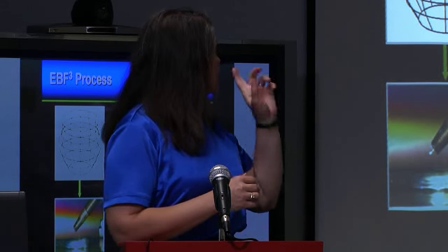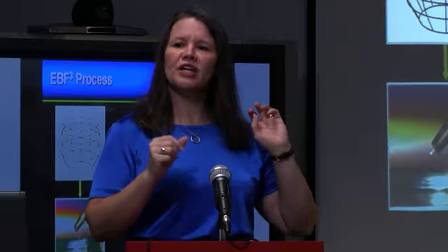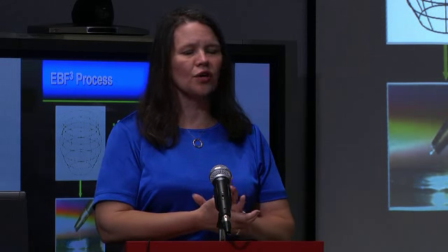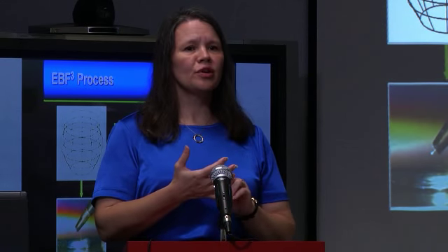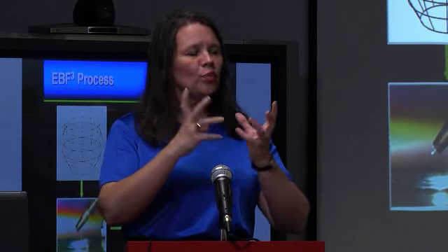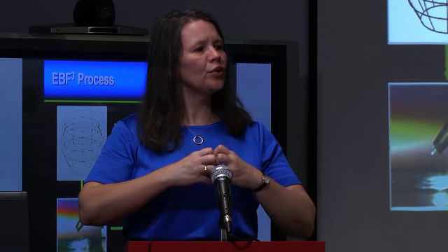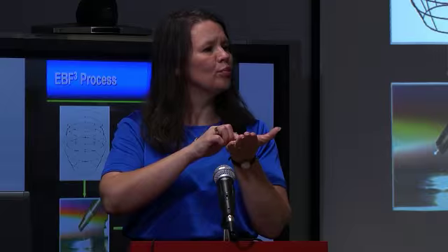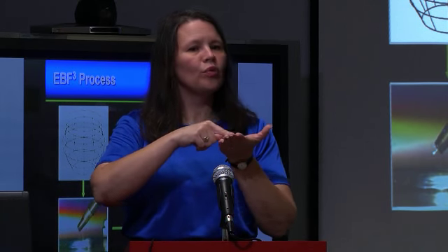So I've pretty much already talked about this. Some of these pictures do not show up very well on the remote locations, but you will have all of these charts for you to be able to reference on your disks. We start with a CAD drawing, a computer-aided design drawing. You build that 3D part on the computer, and then we use an electron beam to create a molten pool, feed wire into that molten pool, and then translate the whole thing, and we build it up layer by layer.